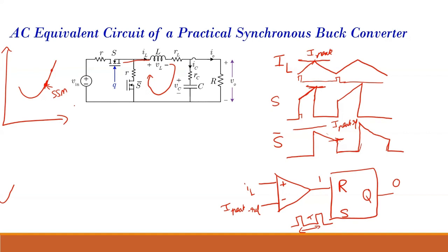See, we use small signal model because it is linear, and if we want to use linear control techniques to design the controller and to analyze a system, then it is required that we should have a linear model. And our DC-DC converter is not a linear model; it is a non-linear system.